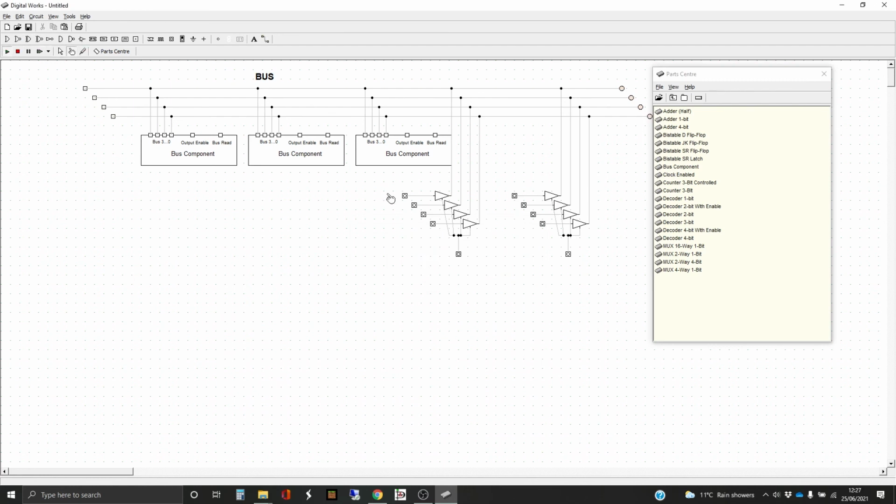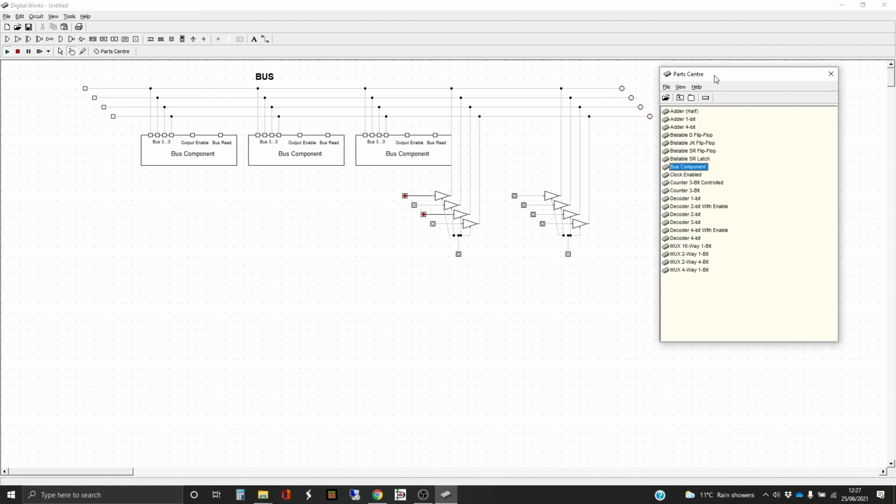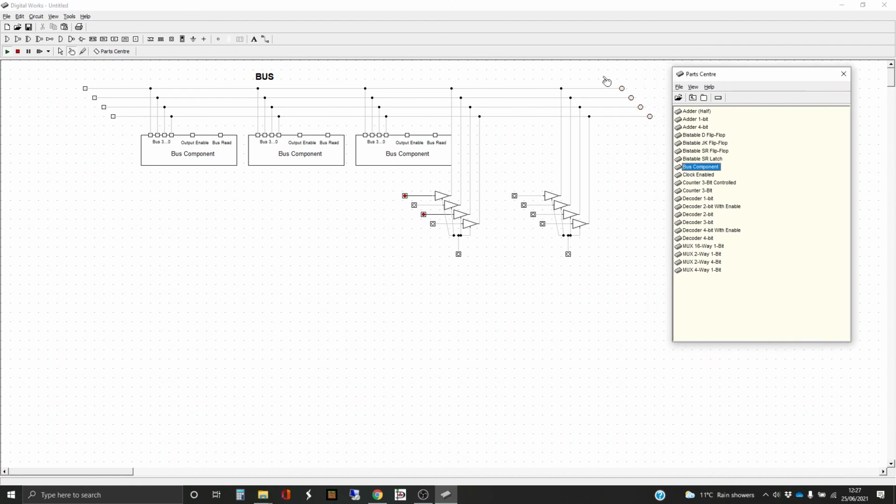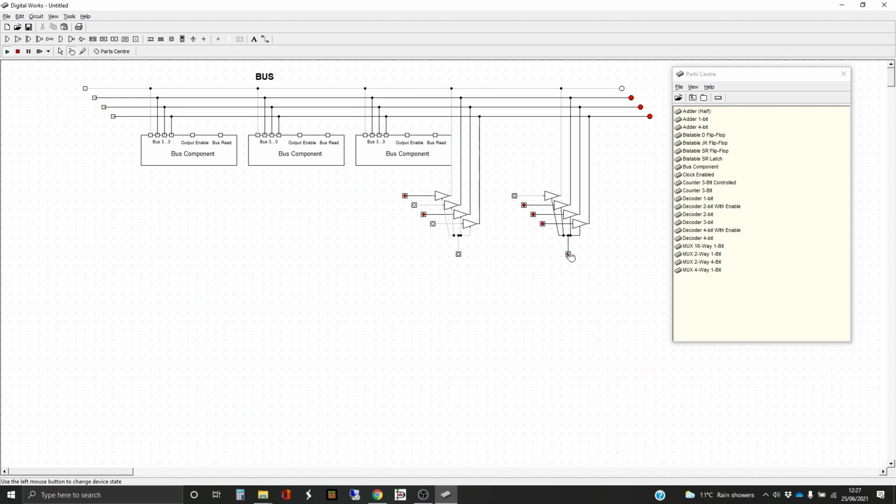So we've got two 4-bit input things here, and I'm going to put the number 10 on this one. And when I hit this, it should enable it to the bus. And this bus happens to have LEDs on one end of the wire. I tend to do that quite commonly so that it's easier to keep track of what's going on. And on this, I'm going to put the binary number 7 instead. And so when I hit that, it sends that to the bus.